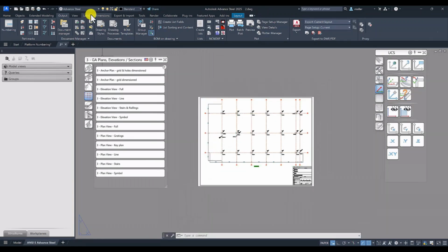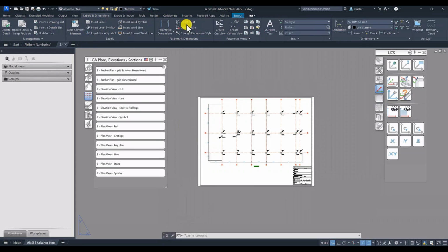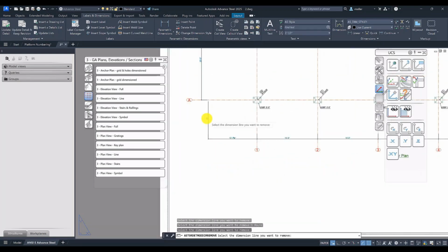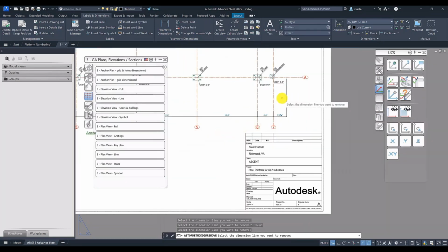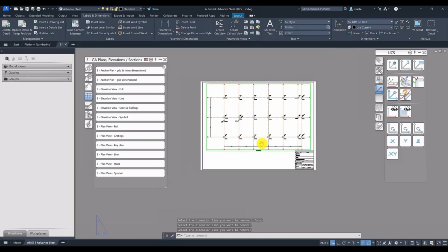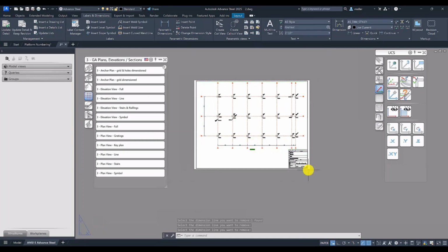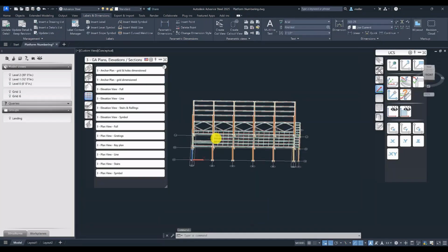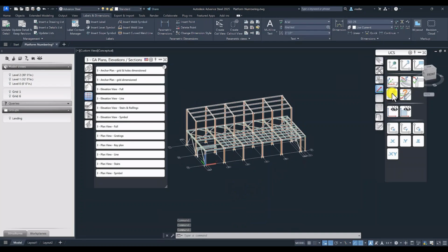It did some really weird dimensions, but we actually have what is called parametric dimensions inside of Advanced Steel. So when you're adding or changing dimensions, you need to go through parametric dimensions, not AutoCAD dimension tools. The only thing AutoCAD's dimension tools are used for is the dimension style, and that's about it. Yeah, perfect. Simple to fix up. Okay, looking good.